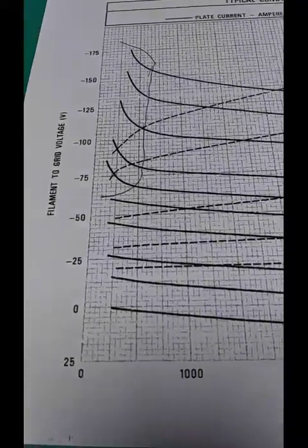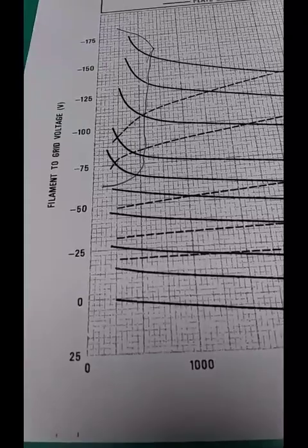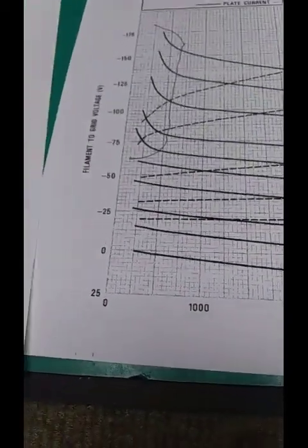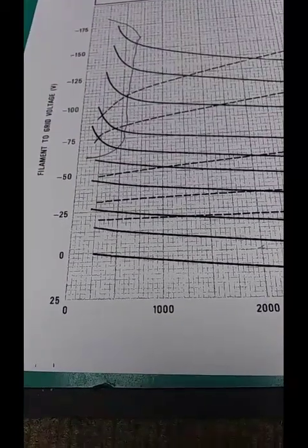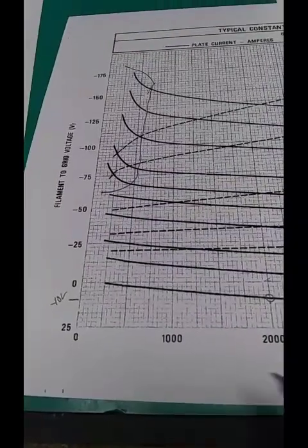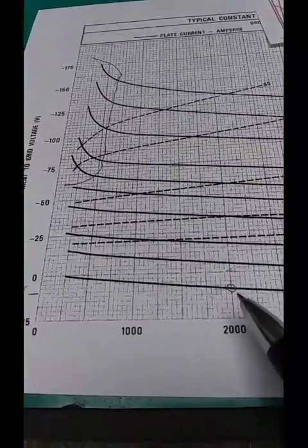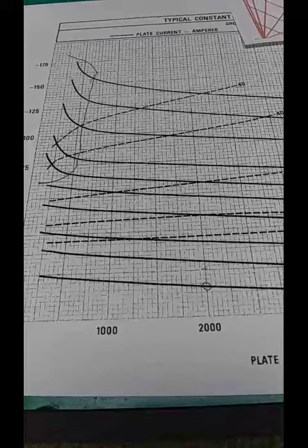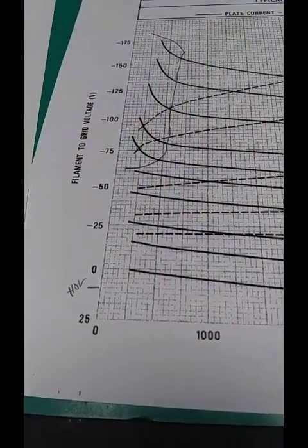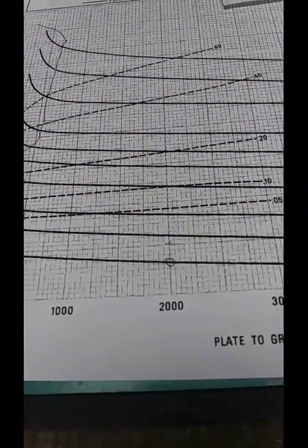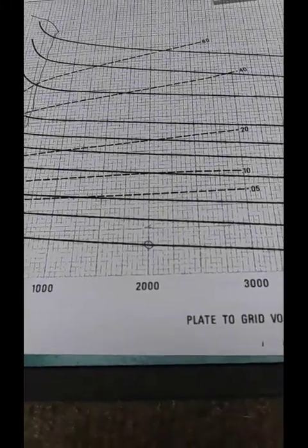What happens is that in operation, the grid voltage is swinging from probably around 80 volts minus, down to 0, and 80 volts plus. So with this grounded grid amplifier, with about an 80 volt swing either way, the grid voltage is guaranteed to go through a condition where at minus 10 volts on the grid, at 2 kV plate voltage, the plate current is 0. It's guaranteed to go through that condition. Oh, correction, that's plus 10 volts. Down is the positive direction. It will go much further than that into cutoff. So the load line must start at the intercept between 2000 volts and 0 amps. And I'm going to end this video and start with part 2 next.